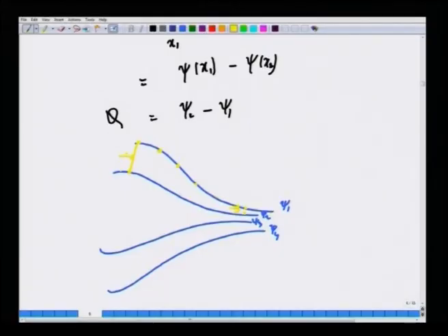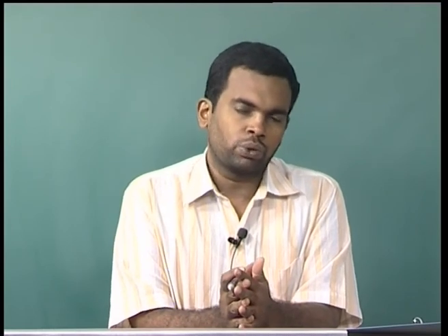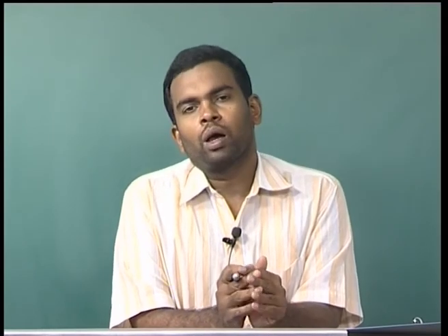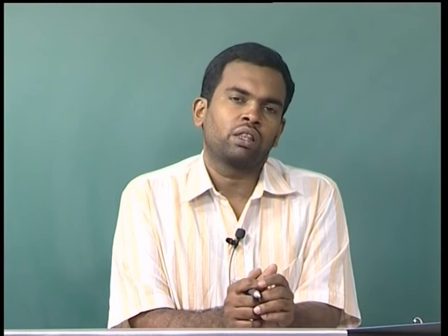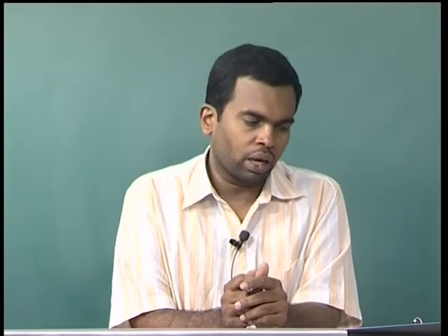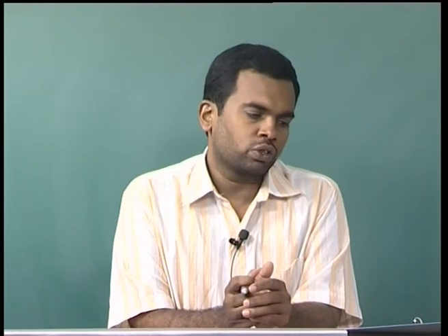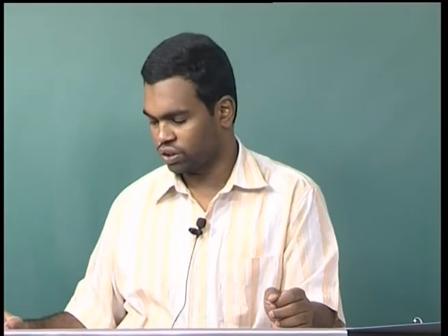So, this gives rise to a very quick aid for flow visualization, because once you have a huge amount of data, let us say from a computer solution or an experiment, by plotting all the data in terms of streamlines, one can immediately get a qualitative feel as to where the flow velocities are large and where the flow velocities are small. So, this is the big advantage of the stream function.